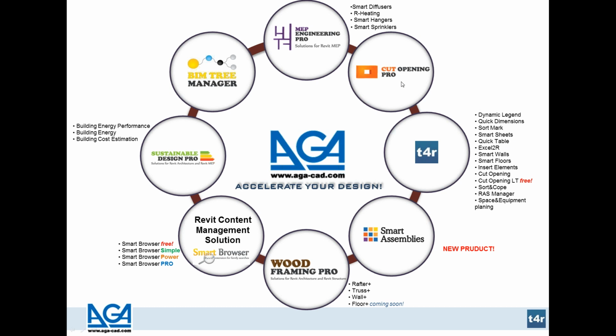The other thing is Cut Opening Pro. This tool cuts the holes, the openings around your needed elements. For example, you have the ducts or something like this, and you have to cut the opening around it. So you don't need to work on each element separately. You only have to display what you need and click some buttons, and all the openings in the whole project will be done.